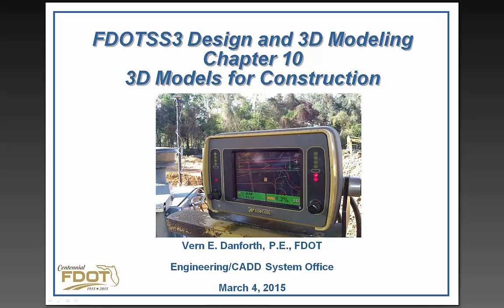As you can see on this image, this shows the actual equipment down here. This is the actual project site as it would appear on a 2D plan sheet. And then it's also tracking the proposed surface for this particular project, and it helps the grader decide what the depth of the blade needs to be on the existing ground, and so on and so forth. This picture also shows the receiver here that's mounted to the equipment.